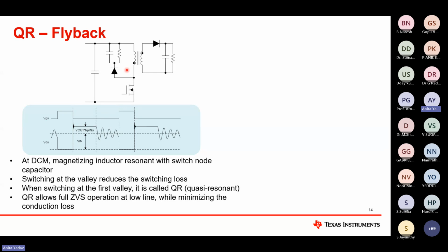So if I have a 200 microhenry magnetizing inductance, then 3% is 6 microhenry. Even if I have parasitic caps of, let's say, 100 picofarad, we will end up with almost 1.6 megahertz frequency here. So it's a very fast oscillation.